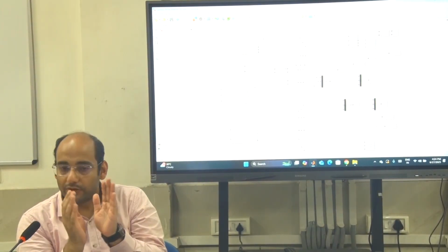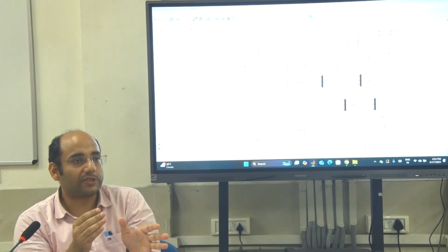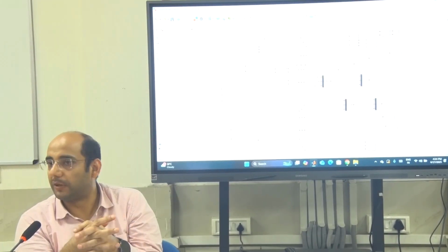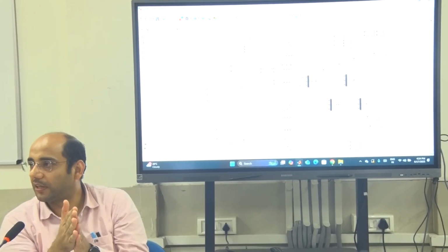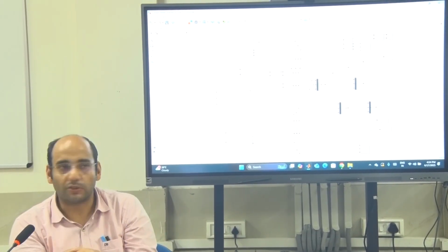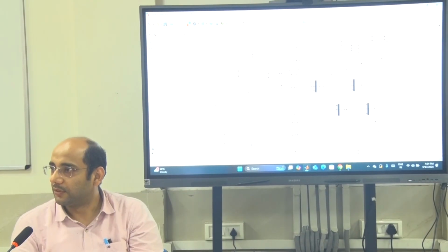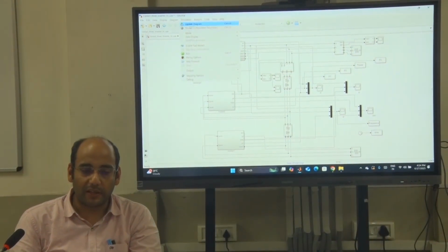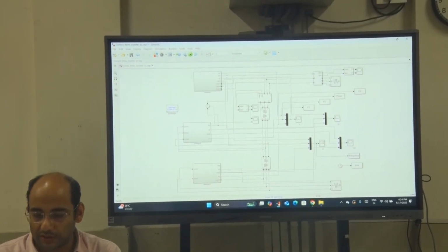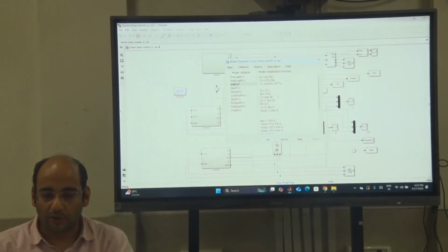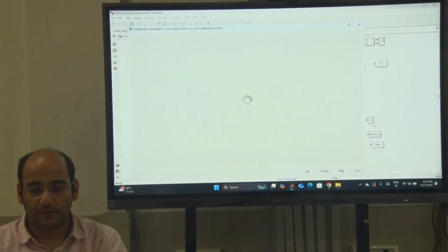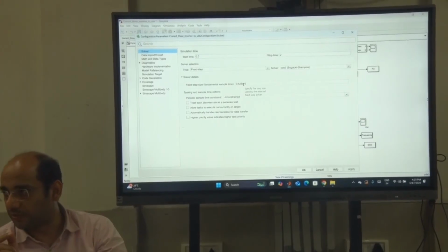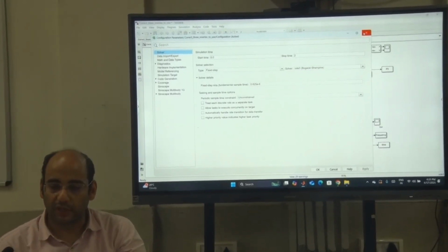Okay? If you consider all of these things, you decide a proper sampling time, then you do the simulation, then you can think that your simulation results will be correct. Otherwise, you just keep doing something and you may get some results, but all those results will be wrong. So that is why, for example in my case, I have put a simulation sampling time of 0.625 microsecond, because probably I have taken a switching frequency of 8 kilohertz.